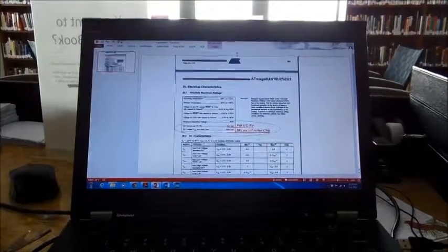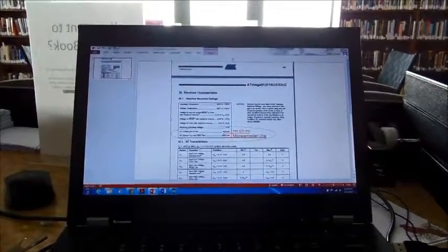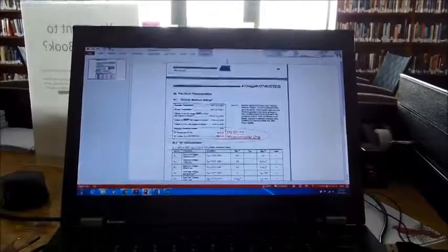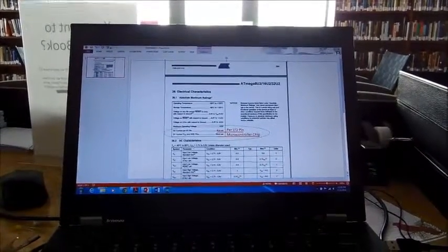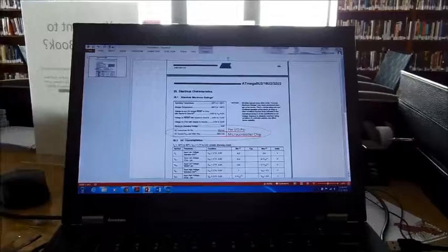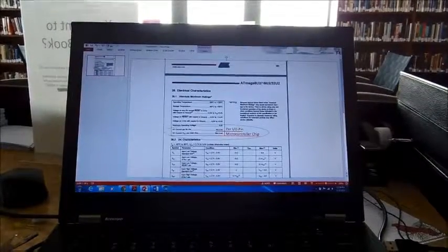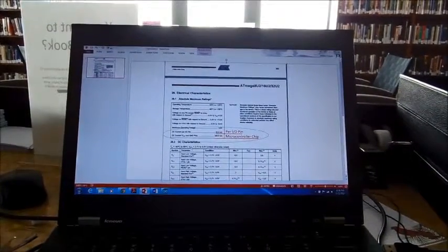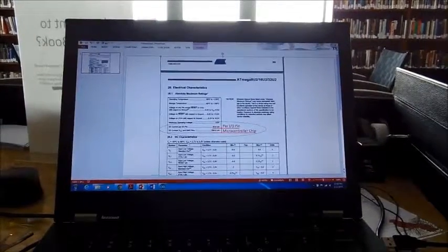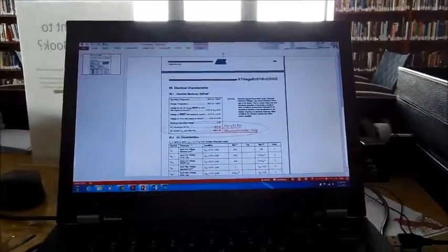obviously our output pins cannot drive the motor since the motor is running at about 100 mA. So we have to drive it either directly from the battery, which we were doing there, or what we're going to do now is drive it from a FET, and we'll see how that works.